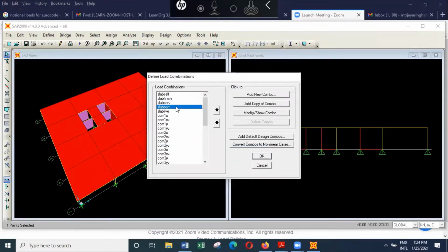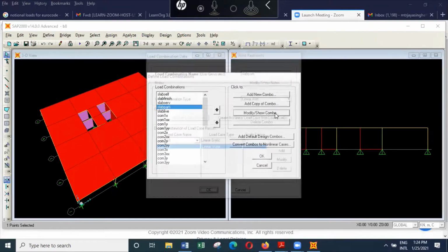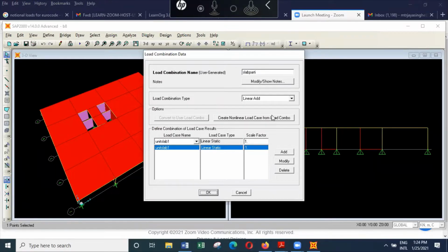And then we can also look at partitions. If you look at Eurocode, depending on the weight of lightweight partitions per linear meter, they give different values like 0.5, 0.8 and 1.2 kilonewtons per meter squared.